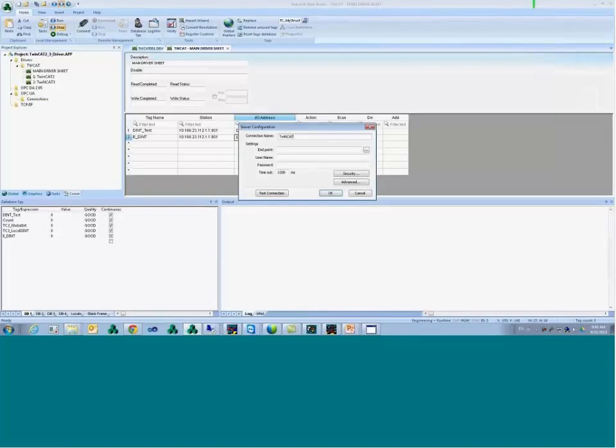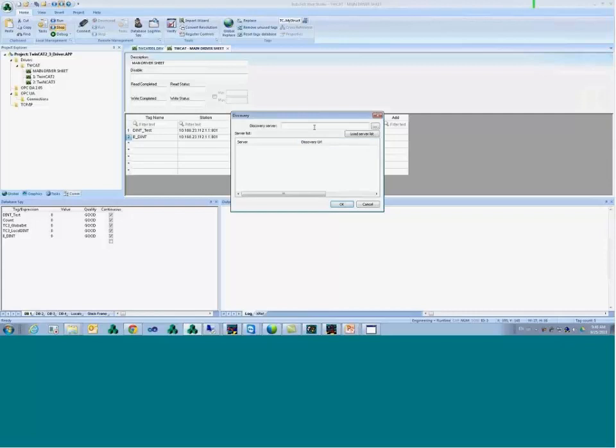Let's say TwinCAT here, and I enter the endpoint, the URL, opc.tcp:// my computer, winxp, and the port number 4840. Okay? Or if the discovery is working, I can put OPC here and load the servers list. You would find all the UA servers that are available, which in my case the discovery is not working.